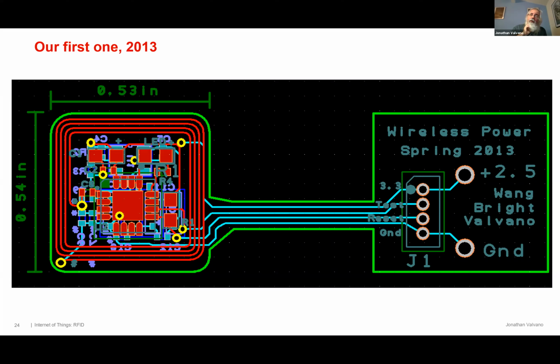Yes. There's an A to D converter in that chip, right? That big red chip, that's an MSP430 with an A to D converter in there, because I'm going to measure stuff. But while this is powered, I have that high frequency coil activating. And so what do you suppose happens to the signal to noise ratio of my A to D converter? It goes way down.